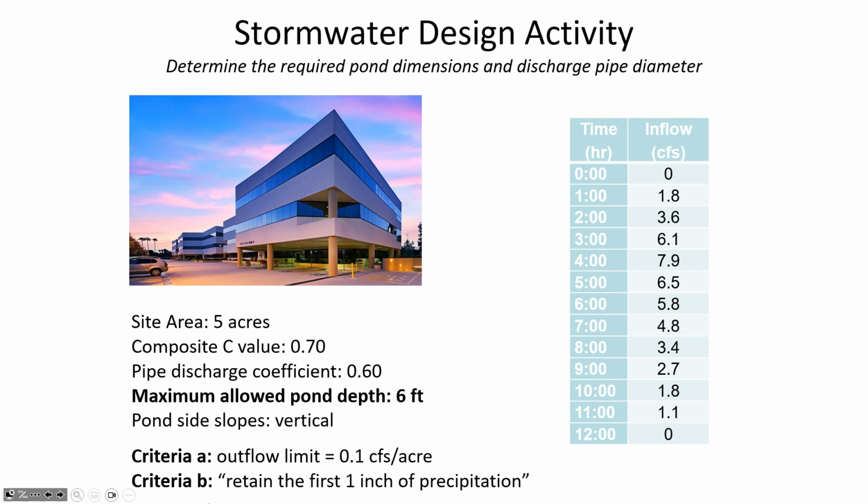And I think this second criteria is the standard that was applied when they built the new football practice facility on 3rd Avenue. They had to have a bunch of underground stormwater detention in order to receive all the water that comes off the roof of that practice facility, and they had to put enough volume there so that 1 inch of rainfall depth over the area of the roof, there had to be that much volume underground for the stormwater to be stored and released very, very slowly into the storm sewer.